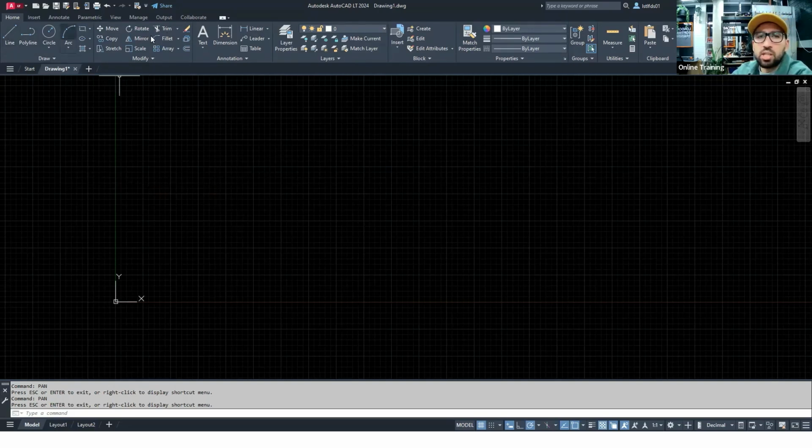I rarely use these commands by clicking on the buttons because I use shortcuts. Shortcuts are substantial in AutoCAD. There are quite a lot, but they're quite easy to memorize as well. They are usually the first letter, 2 letters, or 3 letters of the command you want to use. Line, you just write down L, enter, and you are in the line command. Circle, it's C, enter, and so on. They might overlap, so you might need to write down more than 1 letter, but don't worry, when we practice throughout the course, you're going to memorize most of them. In the resources folder, I have an A4 sheet that has most of the commands. You can print it out later on, keep it on the side. You can just use it as a reference.